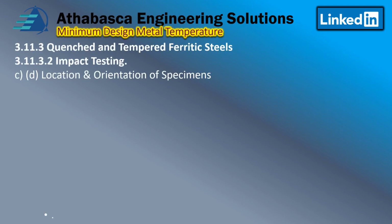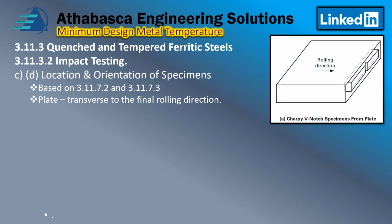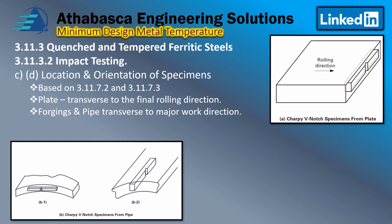As we continue to look at C and D, location and orientation of specimens, the requirements are based upon 311.7.2 and 311.7.3. For plate, the impact testing must be transverse to the final rolling direction, just like shown in this diagram here. And the forgings and pipe must be transverse to the major direction of work. So that would be like the case shown there.